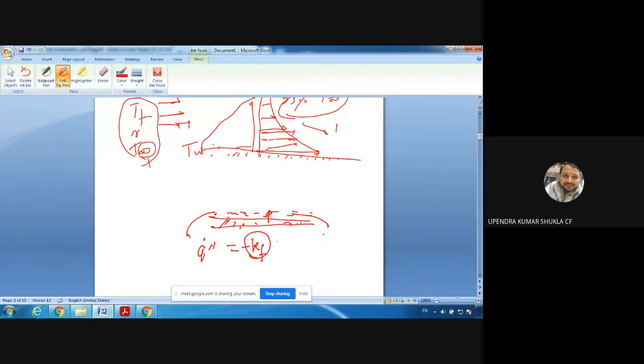Must remember, because fluid layers become stagnant due to the no slip boundary condition, del T over del y at y equal to 0. Here we are taking y in this direction, x in this direction, so y is equal to 0. This will be equal to, now this heat, due to conservation of energy, will be convected away.